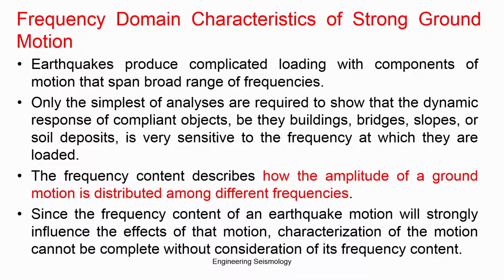The earthquake produces complicated loading, with components of motion that span a broad range of frequencies. Only the simplest analyses are required to show the dynamic response of objects like buildings, bridges, slopes or soil deposits, which are very sensitive to the frequency at which they are loaded. Different structures have their own natural frequency. If the earthquake frequency and the natural frequency are very close, you will get a very large response and may also get resonance. So depending on the building we design, you need to identify what frequency range of the data you will be interested in for the analysis.